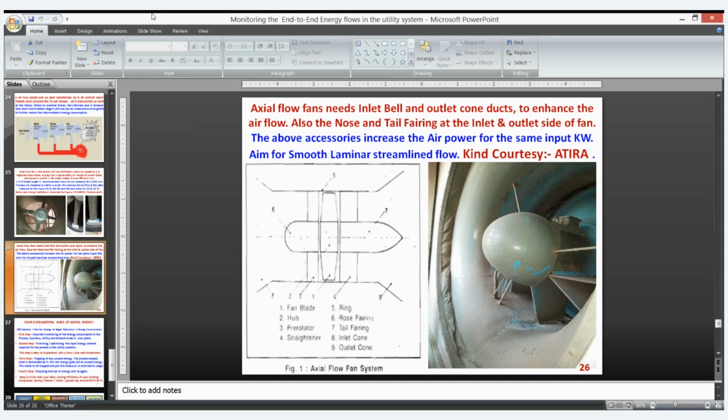Why are we using velocity recovery rings for all the HVAC cooling towers? The velocity recovery ring tries to restore the turbulence of the flow outside the condenser fan, and that needs to be there not only for the heavy duty 400 ton or 60 ton cooling tower, but even for a 1.5 ton split AC. On the high side outer unit, you can have a velocity recovery ring of a few inches. If it is fixed on the fan, it will definitely tell upon your fan efficiency. It improves your condensing, and the heat transfer efficiency is improved on the outdoor fans also.